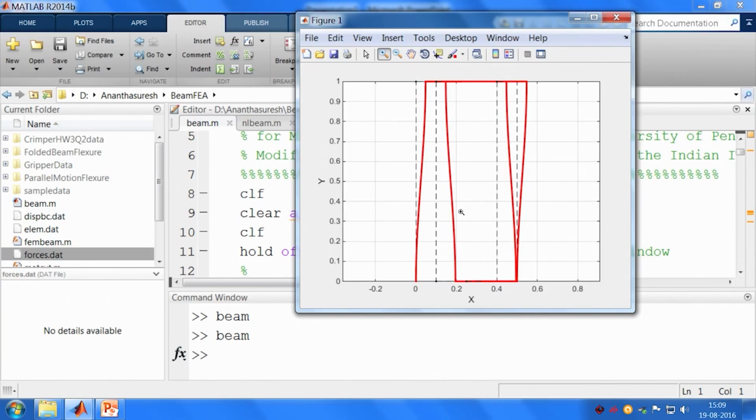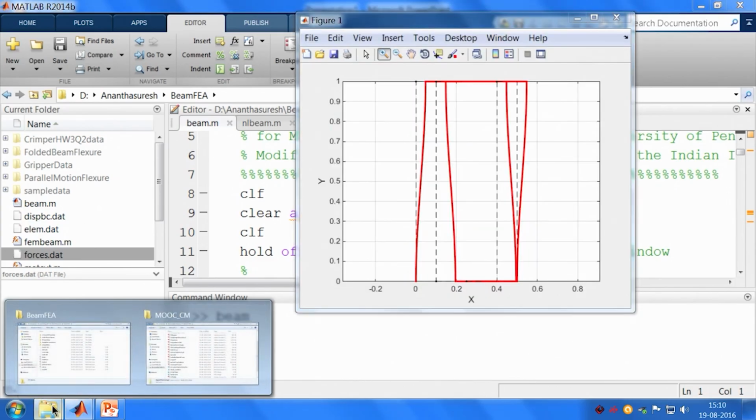But what we learnt now is, if you have finite element analysis code with you, you can generate the lumped stiffness matrix for any rigid segment that you have, or even a point. At that point, how does it feel in x, y and z directions. So, you get the cross axis stiffnesses also as part of this, or you have to do 3 finite element analysis in 2D and 6, because in 3D, because in 3D you have 3 translations and 3 rotations, all of that you can get.